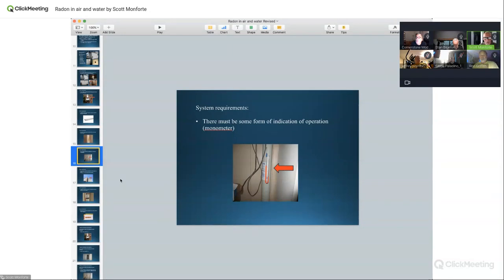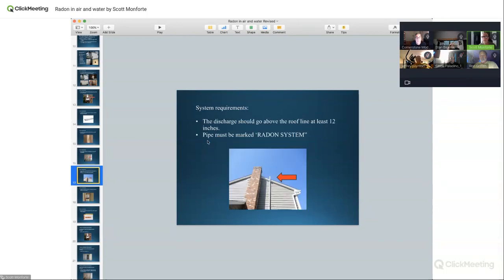The other thing too is when you pull up, let me see here. Okay, here's the one. The pipe should be not a 90 below the soffit, not on this two-story colonial that has no windows on the side, where the guy was lazy and he didn't have a big enough ladder to get all the way up top. The pipe should go above the highest eave.